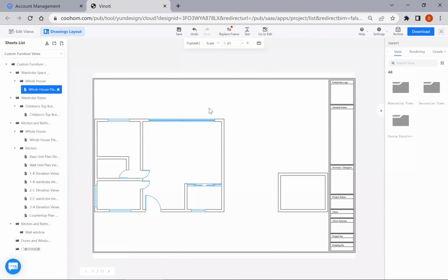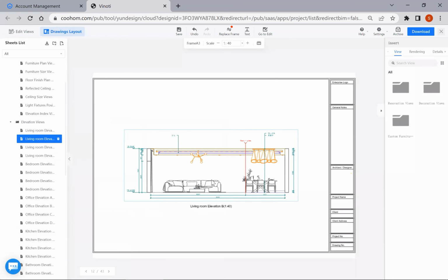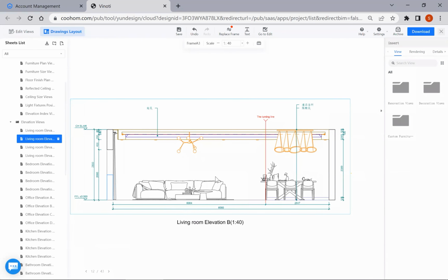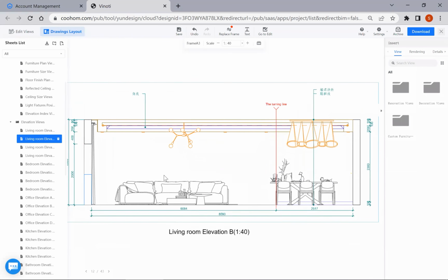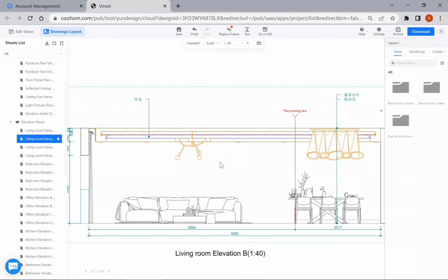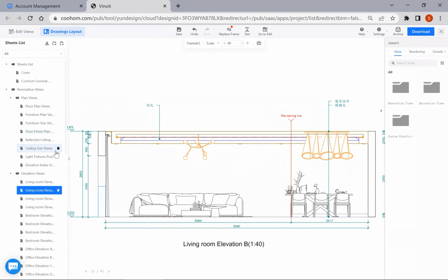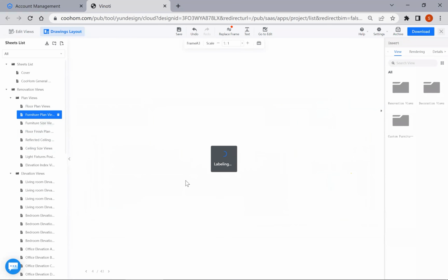But shop drawings are very particular in terms of dimension, even 0.1, 0.2 on the setting out line, because your construction drawings are very basic. So it's a blow-up detail. Can Coohom provide that in the system? You mean like the inside? No, on the structure, on the floor itself. For instance, we have 600 by 600 tiles with a gap of 5 mm, the floor finishes. So every dimension of the tiles is labeled.